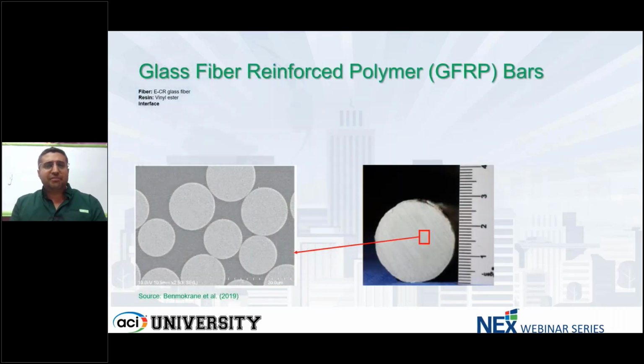For those who don't know what GFRP is made of, GFRP stands for glass fiber reinforced polymer. I'm sorry, some of you might already know this, but I have to give a little introduction for those who are new to this presentation and the topic of GFRP. If you look at the picture on the right side, this is an example of a piece of rebar. I assume this is a 29 millimeter, number 9 imperial rebar. If you grab this bar and polish it under a microscope, you will see the picture on the left side. Just for your information, this is about 20 microns, which is roughly a hair diameter. So those fibers are about a third of your hair diameter. The material going in between is the polymer or epoxy that holds these fibers together and protects them from environmental damage. So that's a little bit about fiberglass.